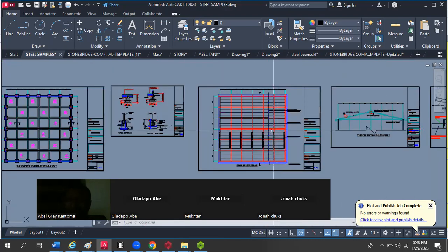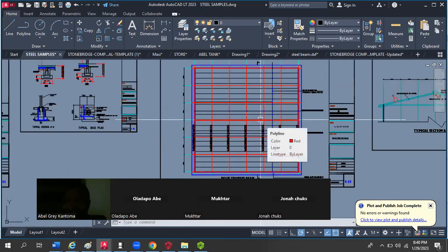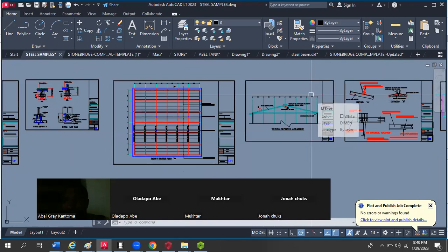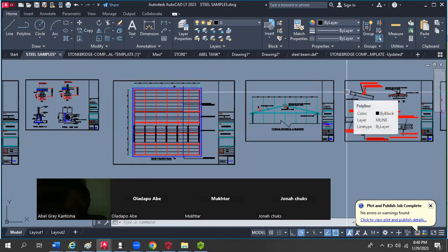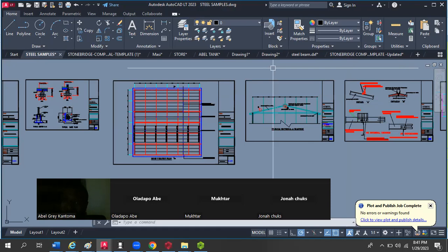Then at the roof level, you generated a pole line. You had a pole line there. Probably you even had a brace there at that level, showing at the roof plan. Then you come to the main cross-section of that particular steel. When you are doing design, the architect has to give you the cross-section. That's why the most important thing to you when it comes to steel, most especially, is the cross-section. In short, that's the most important information that you need from the architect.